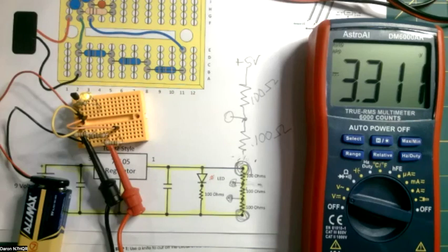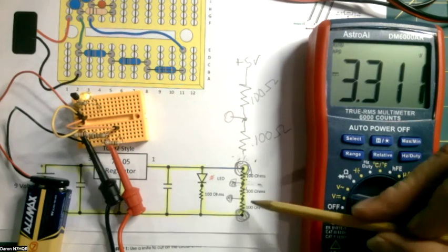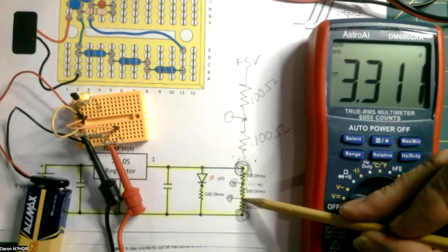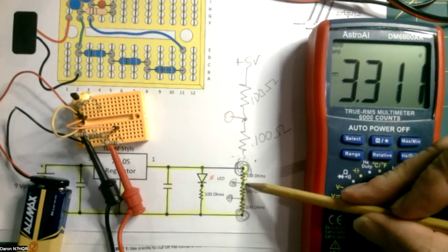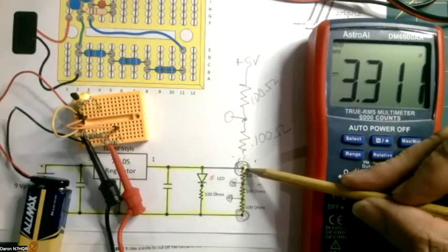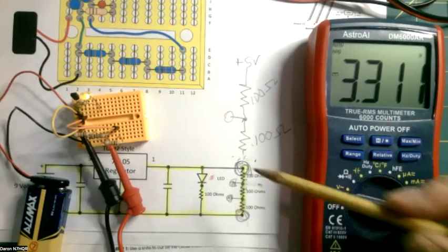No. The current stays the same through the whole circuit. So Darren, just point to the bottom of the 3 resistors. Okay, so there's 300 ohms. That's 0.15 amps going through that, right? So there's 0.15 amps there. Now go to the next node. 0.15 amps there. Next node. 0.15 amps there. Next node. 0.15 amps there. It's always the same.